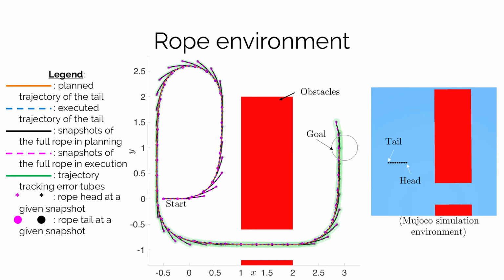Finally, we visualize our results on a 22-dimensional planar rope manipulation task. Controlling deformable objects is known to be highly challenging due to their infinite dimensional state spaces and a resulting high degree of underactuation. We consider an approximate rope which is represented by 10 rigid links and therefore 11 nodes.